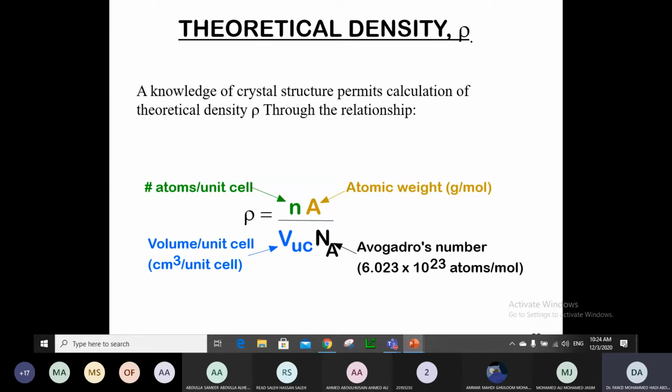If it is a regular shape, then you can use the scale to get the weight, and then you can measure the volume. From that you can get the density. If it is not a regular shape, then you need to get the volume from the volumetric cylinder. So you need to go to the lab and do these measurements.